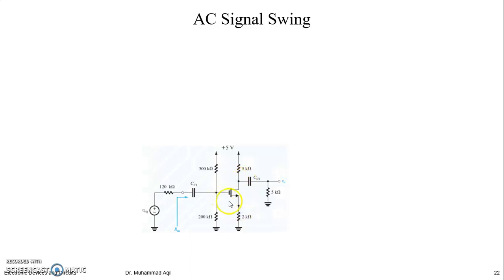For example, for an increase in VGS for this NMOS and for this common source amplifier, when the total VGS increases, ID increases. ID increases, so the voltage drop across these resistances, because ID is through this one and this one, ID multiplied by this and ID multiplied by this voltage will be increased, right?